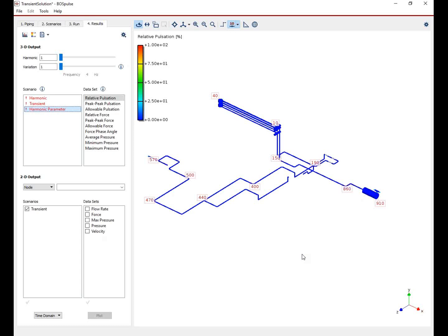And the most important thing I noticed when we were importing those 1,000 isometrics: make sure that all the isometrics are there and that they're somewhat well connected. It's okay if there's a little bit of an offset in the global coordinates between two isometrics. The solver or the routine can fix that.